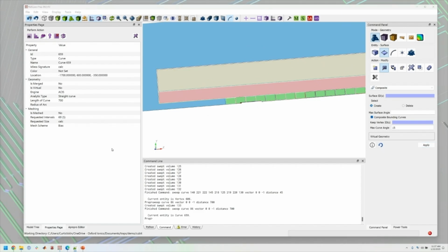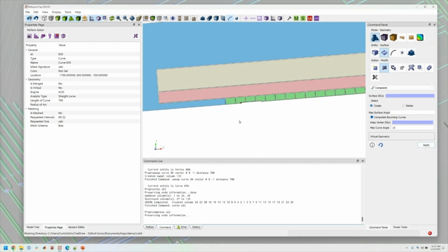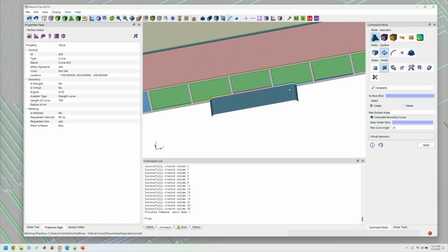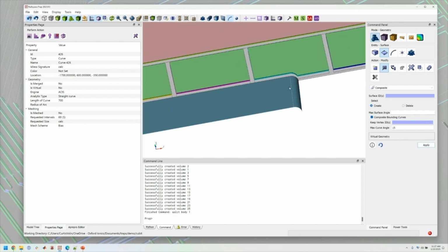So I'm going to run a few commands that simplify the geometry. I think the main thing that does is replace each of these independent surfaces here with one big surface. Notice that we still have a curve here, right? It doesn't recognize these two curves, even though they abut with no angle, or these two surfaces, even though they're next to each other, as being a single surface with a curve at the end. So we will get extra triangles here that aren't necessarily functional from a solve perspective.